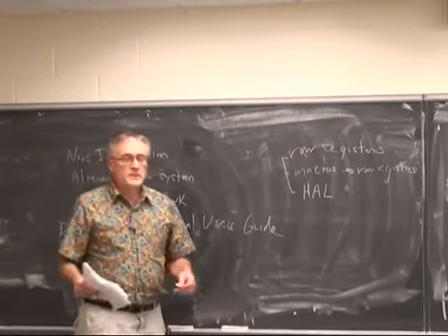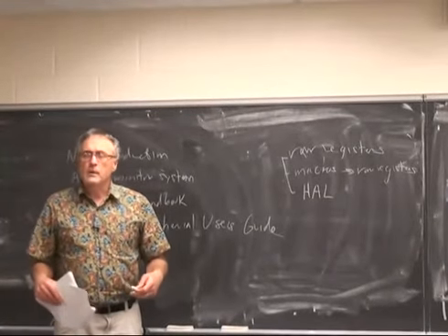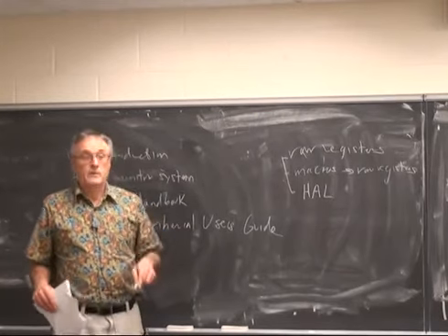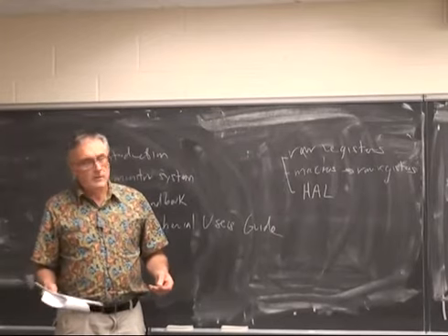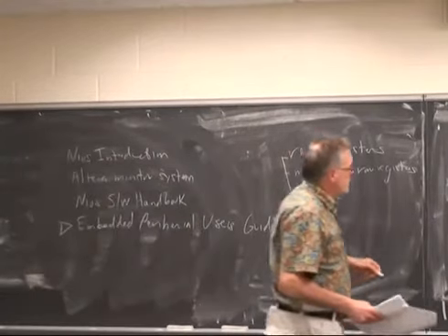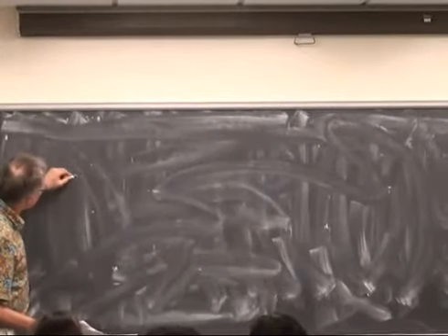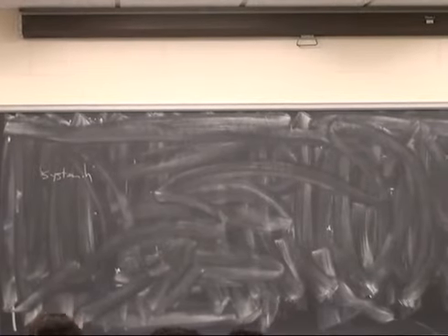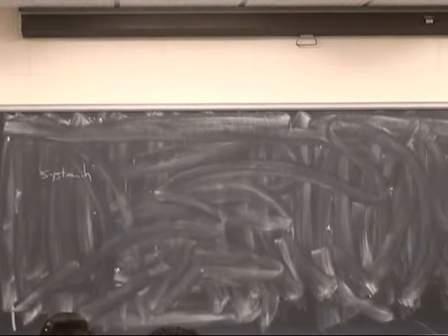There are several places you can find out information about the system you just built. When you run the SOPC Builder and click the Generate button, of course it generates Verilog, which builds your system, but another file, system.h, is also generated, which has a complete description of the system in a sort of human readable form.